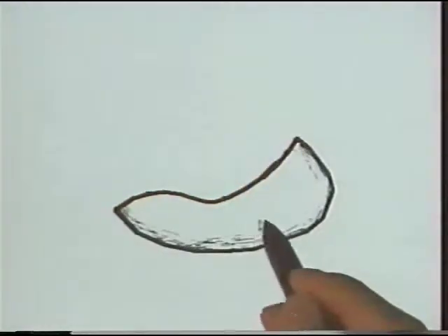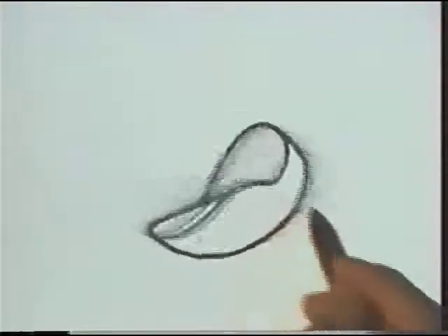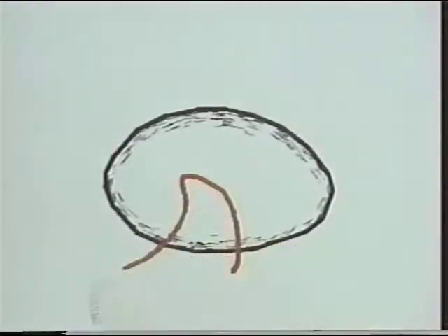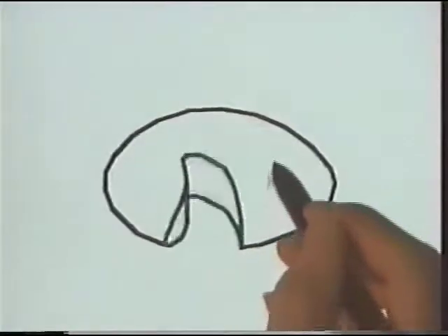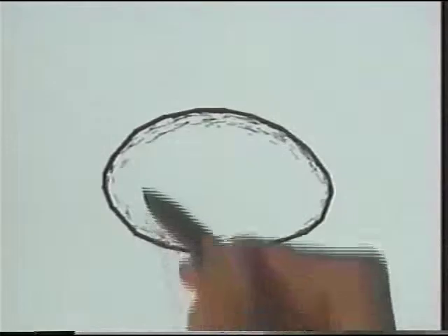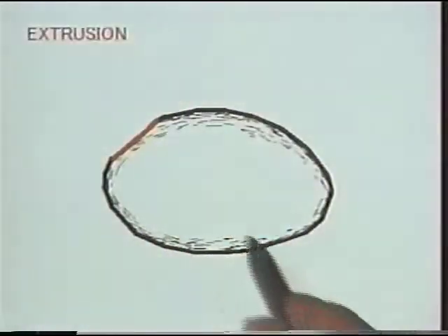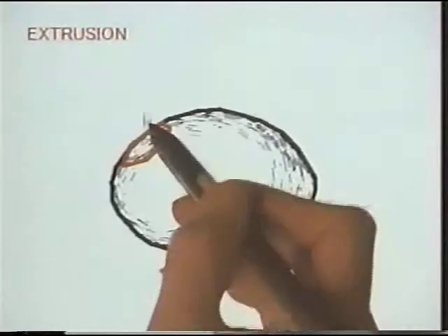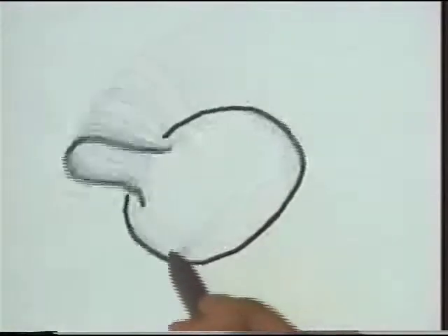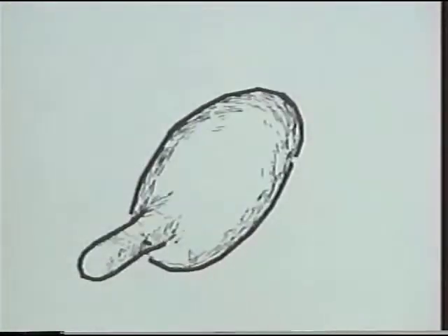You can cut the object by drawing a stroke that crosses the object. With the same operation, you can also take a bite out of the object. This is useful to create a mouth. Cutting stroke makes the cut section red, and you can extrude the section by drawing an extruding stroke.